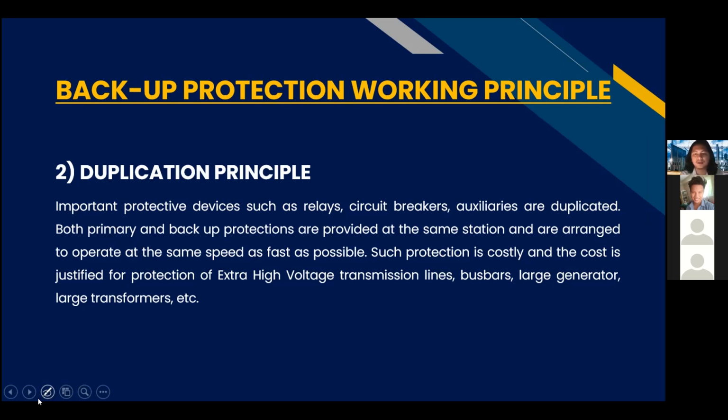As simple as it is, the word duplication explains it all. Duplicating relays, circuit breakers, and auxiliaries in the system in order to protect the system. If the main protection fails, the duplicated protection will operate. But again, this principle is costly.